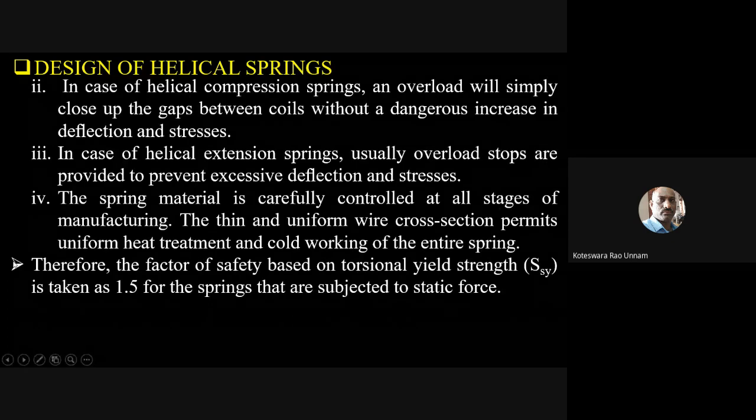So therefore, the factor of safety based on torsional yield strength. Since we are using the torsional shear stress as a design criteria for the springs, you need to consider what is the torsional yield strength, which is known as SYS or SY. Simply S is for the strength, SY is for yield strength in shear.